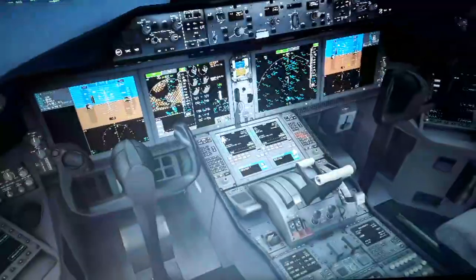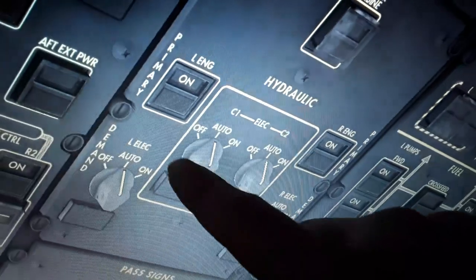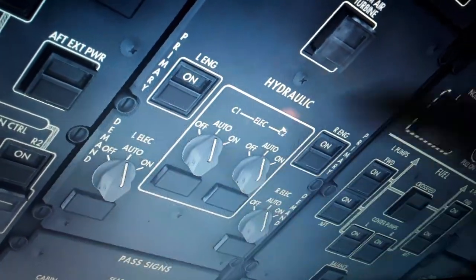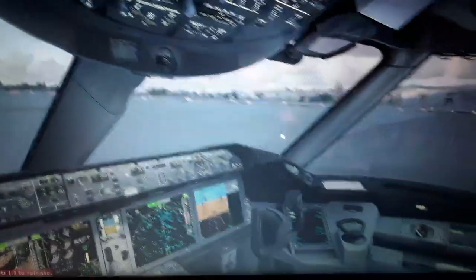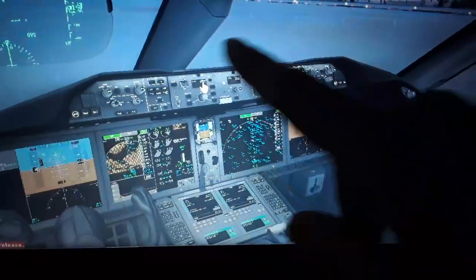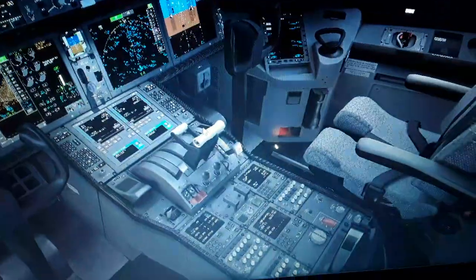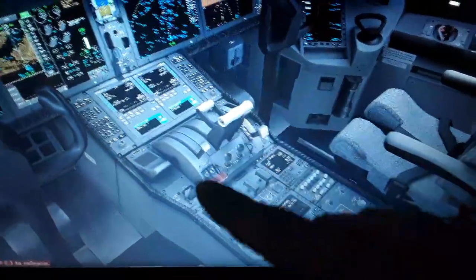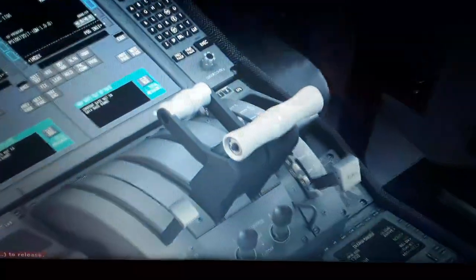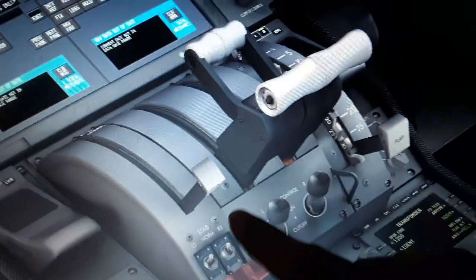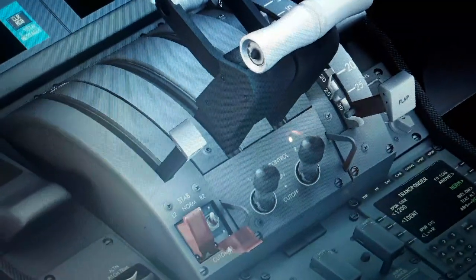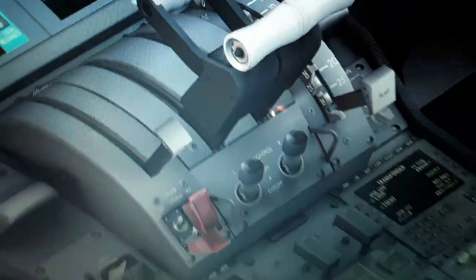If we have a failure of the flight controls system, of the primary flight control computers degradation, because we have some system like the hydraulics, you can see engine driven left and right engine, and electric C1 and C2, we have a failure that affects the flight controls of the aircraft. We're going to lose the automatic trim over here, the auto trim system. This is for Boeing 737, 747, 757, 767, and Boeing 777 and Boeing 787.